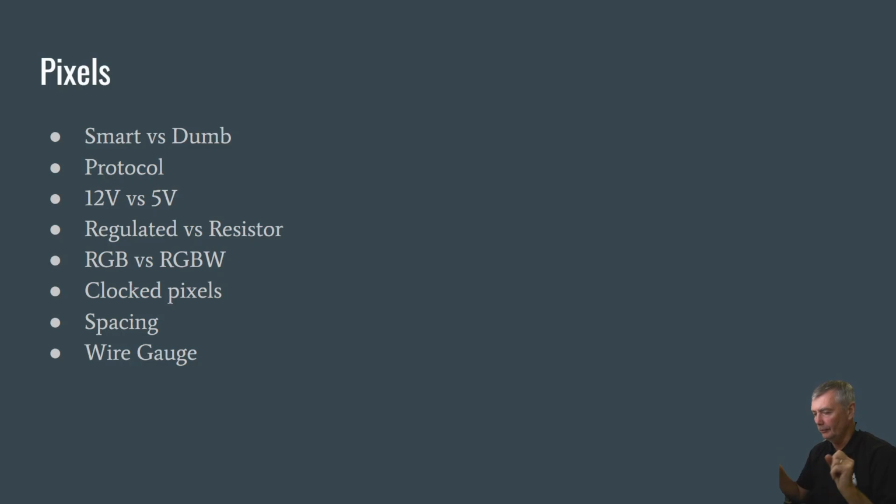So a 3-inch pixel does not give you 3 inches separation of those pixels center to center. Generally speaking, I would add an inch in spacing to whatever it is that you think you need when you measure the center gaps on your prop that you're mounting your pixels on. So if your prop centers need to be at least 3 inches, I would buy 4-inch spacing to give you that little bit of extra space.